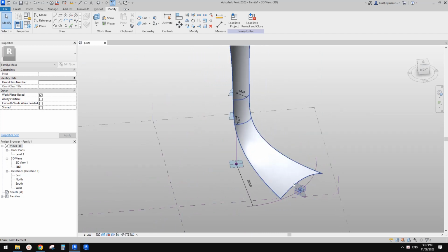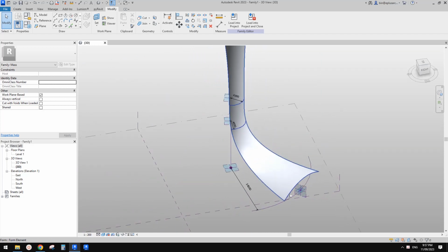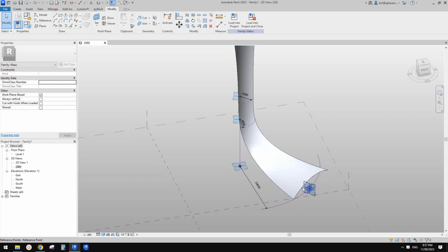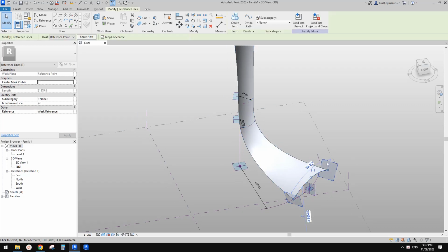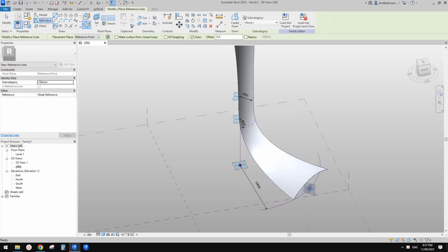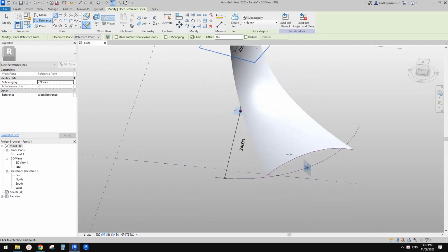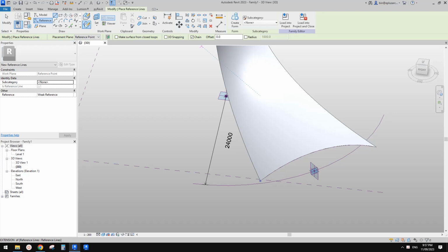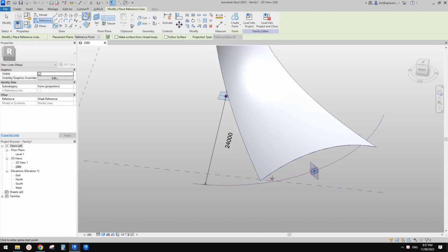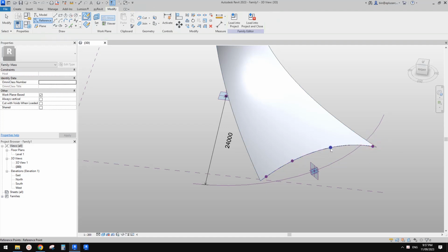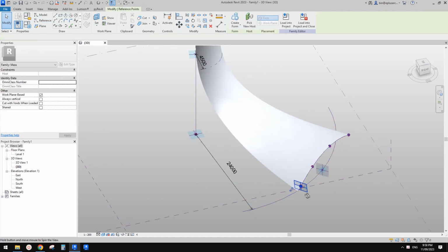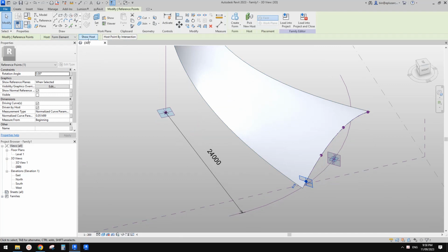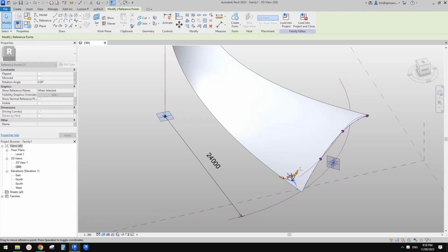Or you might say, oh, can we just do it? We can, but we need to use a different method. So we might need to use spline through points instead of spline, which I'll quickly show you. So I'll just quickly do a spline through points, because if you do spline through points, see this, I'll just change this one to not associate, and then you can make it 3D.